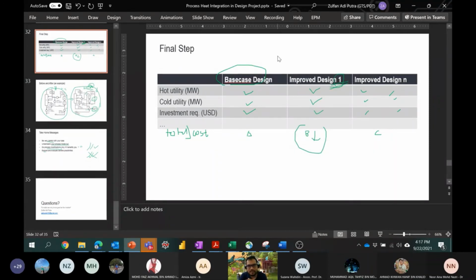In the next phase we do the hydraulic calculations and check the space availability. If it's sufficient, if it's okay, we can then move on to the EPC project, the engineering project, for option 1. If it's not, maybe we have to have a fallback scenario, option 2, for example. Maybe it's not that different from option 1. It's just slightly worse, but it doesn't need more space.